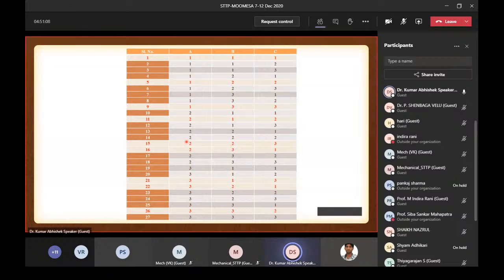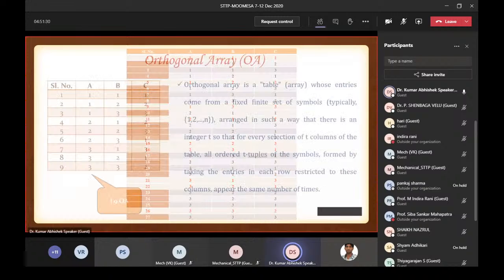if your number of factors is going to be increased, suppose the factor is 5 and the level is 3, then the total combination of experiments is 125. Similarly, when the number increases, your number of experiments is going to increase. So in order to minimize the number of experiments, Taguchi utilizes the orthogonal array concept.